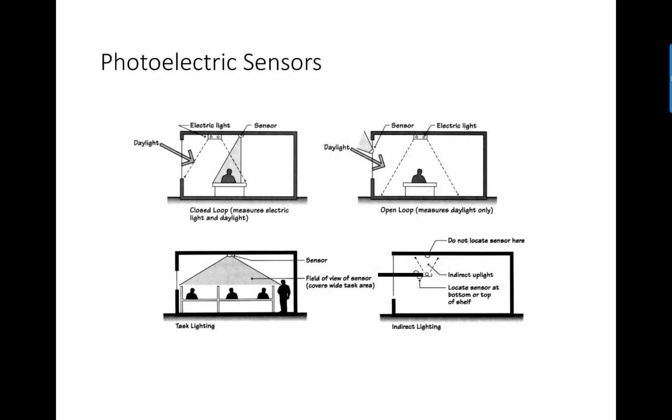You just need to be absolutely careful about where you put these things. Some sensors are sensing incoming daylight. Other sensors are sensing daylight in the room itself in various locations. That sort of decision is really something you're going to want to call in a specialist to help you figure out, because those are quite complicated, and sensor technology is also quite complicated, and then the whole thing needs to be dimmed or switched, and that's quite complicated.